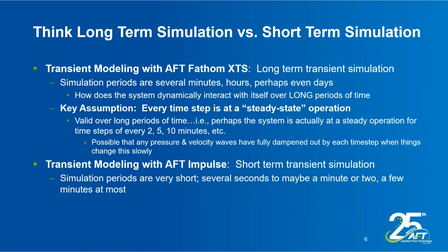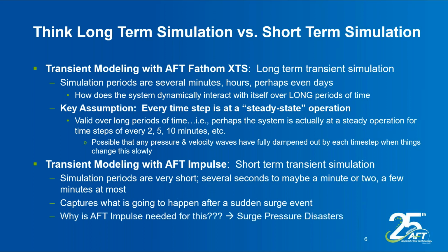And your simulation periods with AFT Impulse are going to be really short. Typically, you're only going to be looking at several seconds after a valve closure or maybe a pump trip. You might look at a minute or two or a few minutes at most, but in AFT Impulse, your transient simulation periods are not going to be very long. They're going to be a lot shorter. And the reason for that is because Impulse is going to capture what happens after a sudden surge event. Why do you need that?